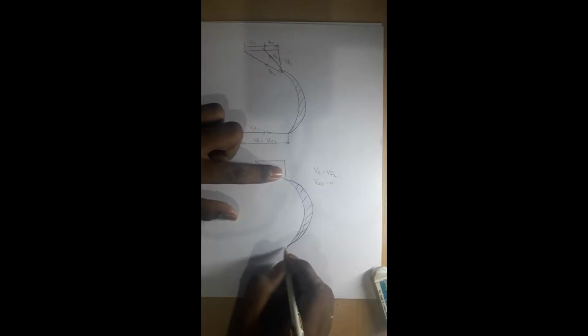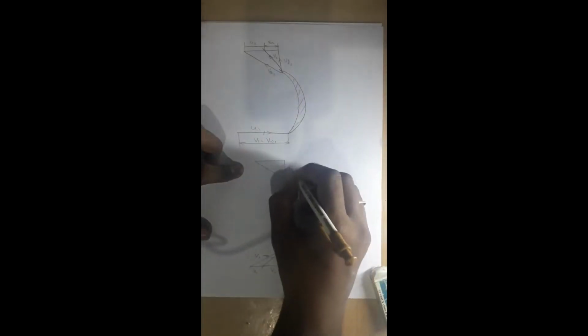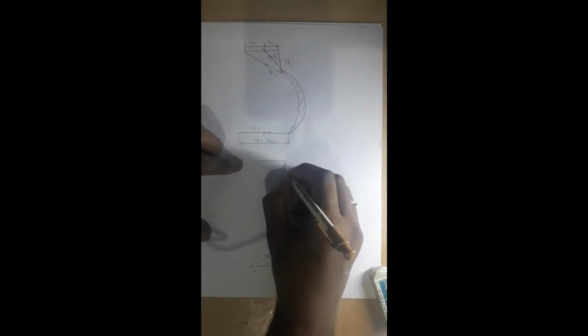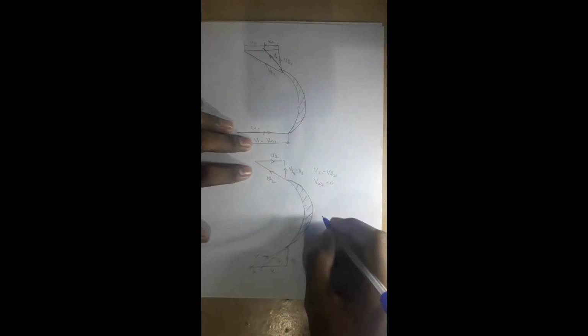And the input conditions remain the same, the velocity triangle of the original plot will be repeated: U1, VW1, VR1, V1, VF1. Here VF2 is equal to V2, and we have only the U2 term and the VR2 term here. So VW2 will be equal to 0. Based on that, the impeller power is also modified in the reaction turbine, as impeller power is equal to